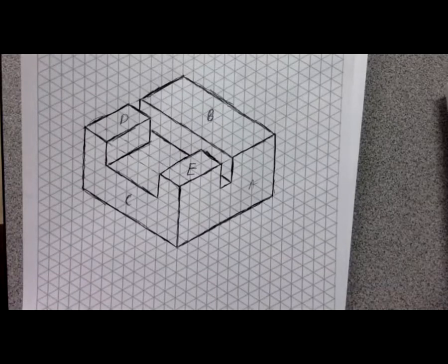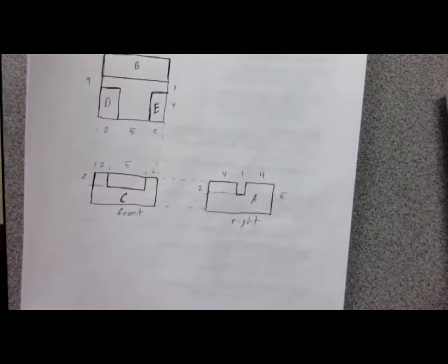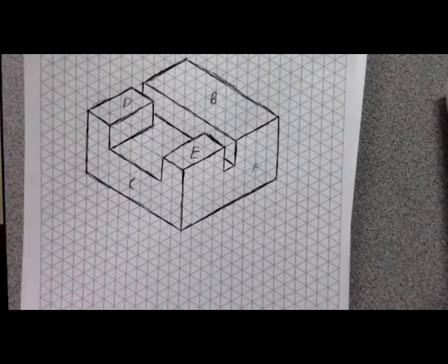We could start adding the hidden lines in here, and it will start getting very busy very quickly. If you don't have to add the hidden lines to communicate what you need, especially on a pictorial, don't. Add the hidden lines as you need them on your projections. But if I don't need hidden lines here, that's kind of what we're looking at. Again, this one's a bit of a challenge, and that's okay. It's okay to talk about how we work through a challenge one.